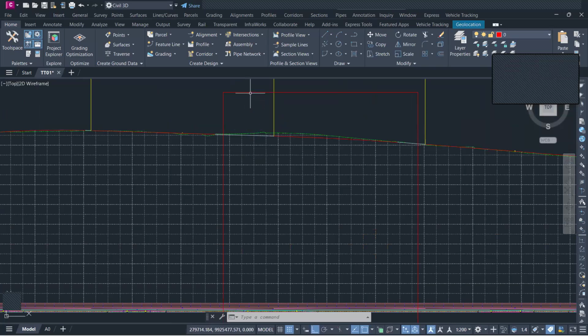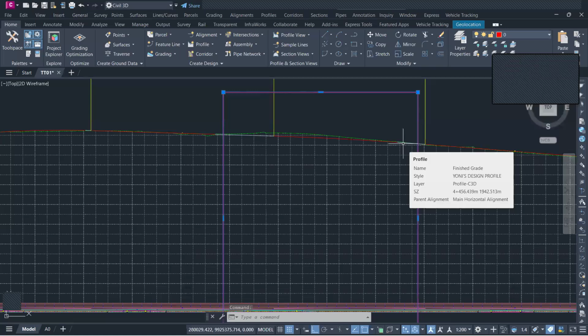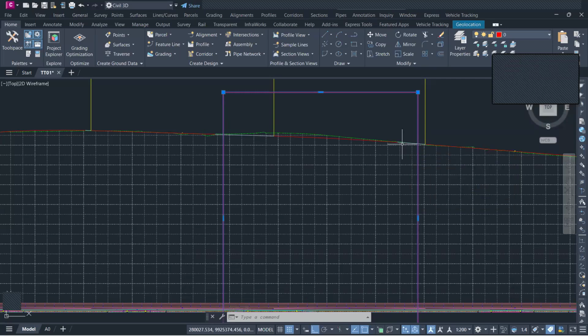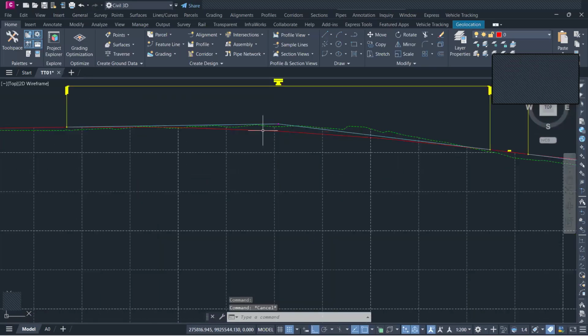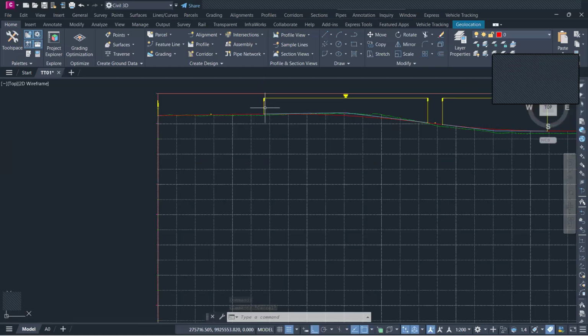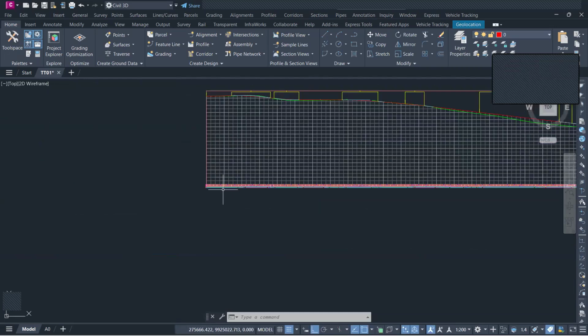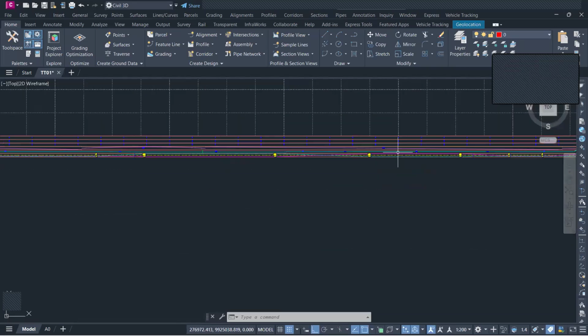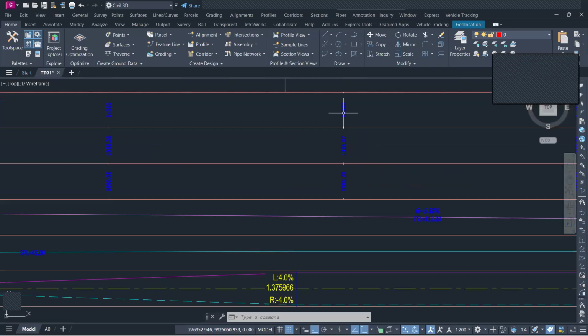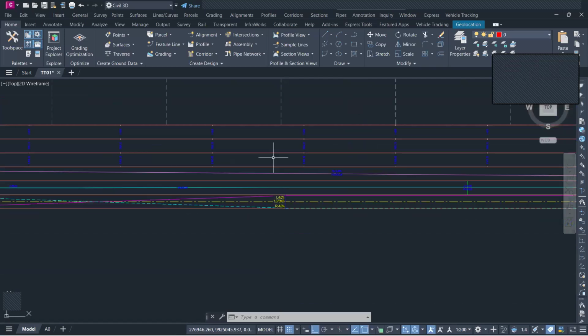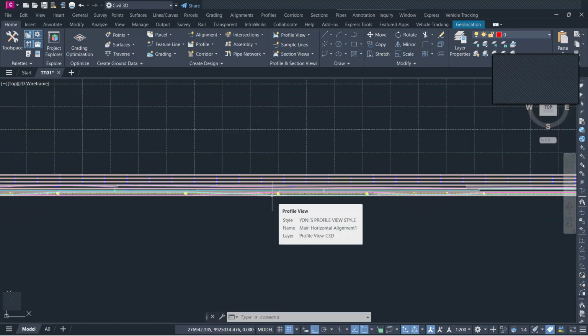So it means as the excavation is ongoing, when you get to this chainage, you cut that material to spoil, to dump it away. But then you will notice, possibly from that report, it will tell you the material at this chainage, this is kilometer 0 plus 120, all the way to, let's say, kilometer 1 plus 380. It is purely good gravel that can be used.